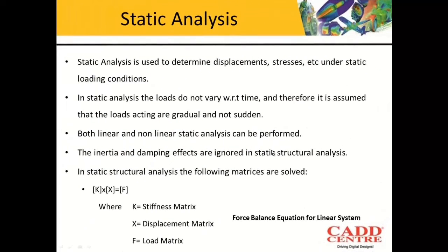First, we will talk about static analysis. Static analysis is used to determine outputs like displacements, stresses, strains, and reaction forces under static loading conditions. Static loading condition means that the load applied does not vary with respect to time, and therefore it is a gradual load.